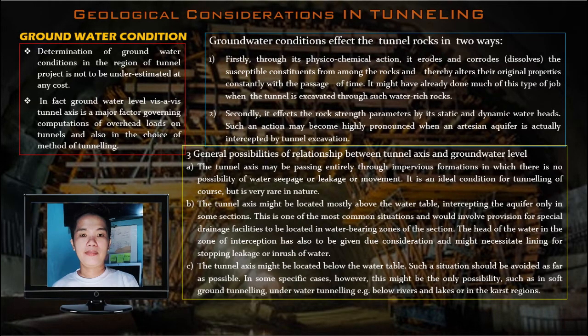The last geological consideration in tunneling is the groundwater condition. Determination of groundwater conditions in the region of a tunnel project is not to be underestimated at any cost. In fact, groundwater level vis-a-vis tunnel access is a major factor governing computations of overhead loads on tunnels and also in the choice of method of tunneling.